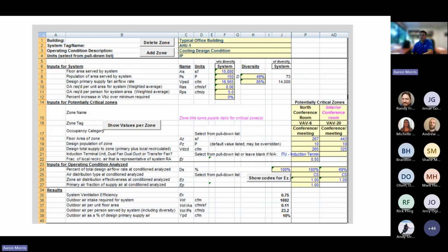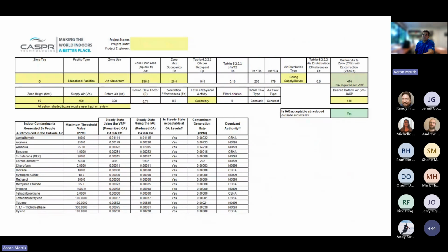Their calculator is not the only one you can use. Several manufacturers have their own. So this is an example, and you can see it looks a little simplified, from Casper, which is one of the manufacturers that Long partners with. It lists those 14 contaminants, actually has a few extras, and lists the threshold values for those contaminants based on the EPA standards, and then already has the efficiencies for Casper's product on how it treats each one of those.